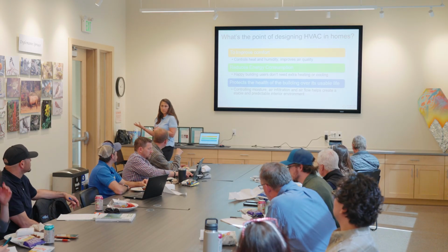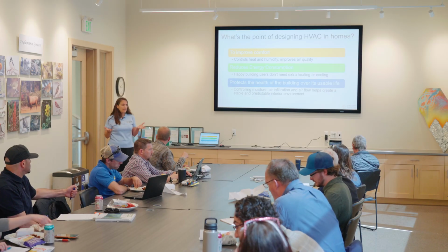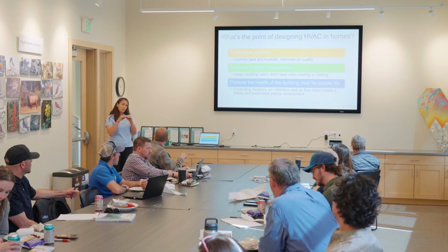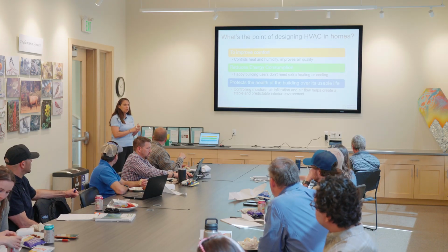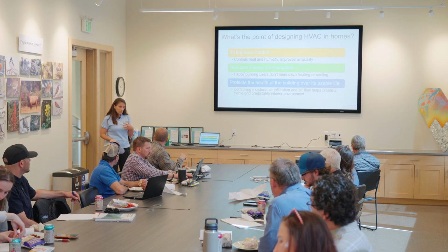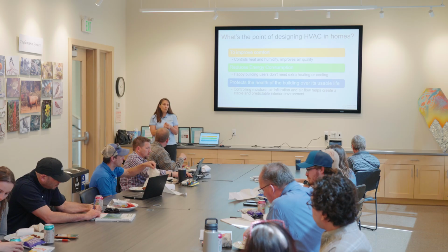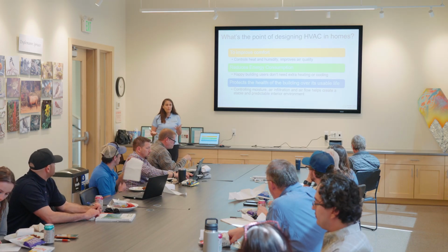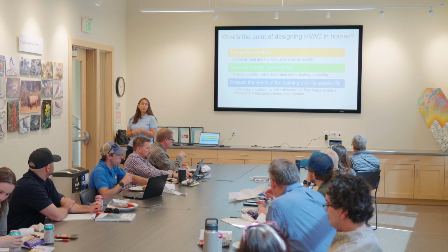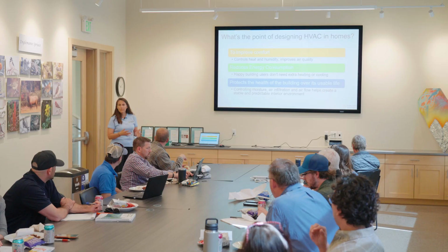Now, the reality is when we're doing all this, obviously the big aspect of the mechanical system is what? If you're a builder, you're thinking, I want to make sure that the occupants are comfortable. And so does the energy code. But the energy code takes it a little bit further and says, hey, we also want you to do heating and cooling load calculations to ensure that the equipment that's going to be installed has been sized to what those loads are.